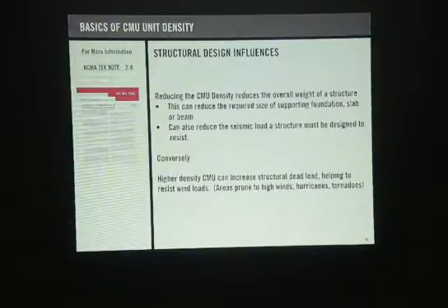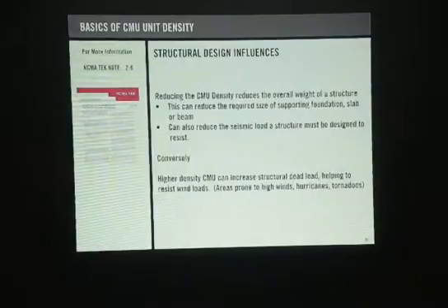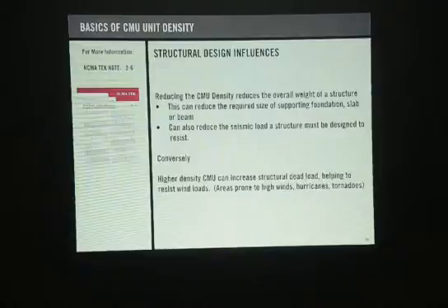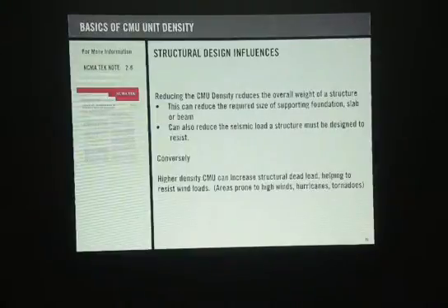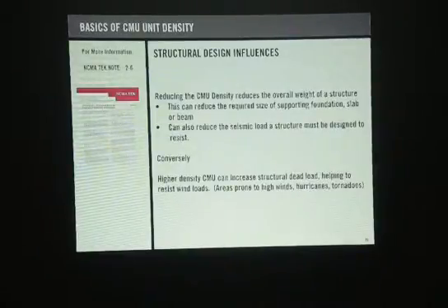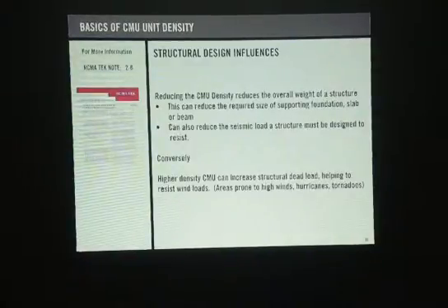Can we add waterproof additives into the concrete block to make it waterproof? Has anyone done that at all? The technology hasn't gotten there, and I don't think it's going to. Bijan, you present a great question. The reason that concrete block is not waterproof is because it needs to breathe, and that's why only water repellents can be effective.